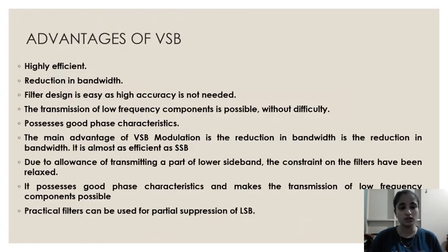Next we move on to the advantages of the VSB. Highly efficient, reduction in the bandwidth, filter design is easy as high accuracy is not needed. The transmission of low frequency components is possible without difficulty. Possesses good phase characteristics. The main advantage of the VSB modulation is the reduction in the bandwidth.